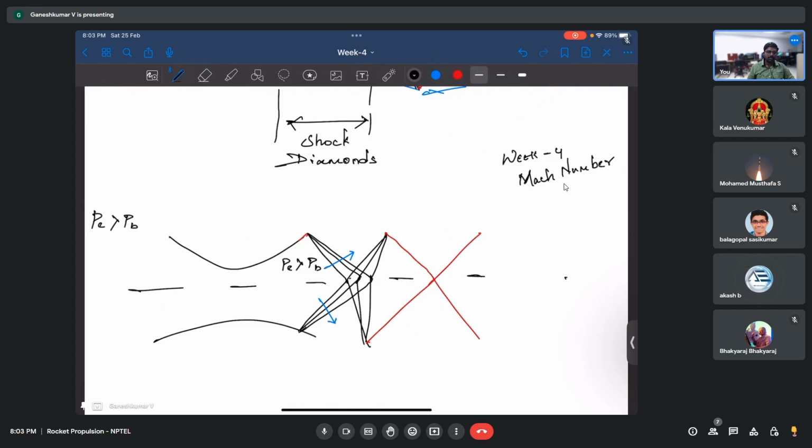But basically, this is the underlying concept you need to keep in mind. If you do not want to reach a subsonic flow, then there is actually no need. You should not put a divergent section at the nozzle, because you are going to reduce the velocity after that, and you do not want that. Why do you need that, right?